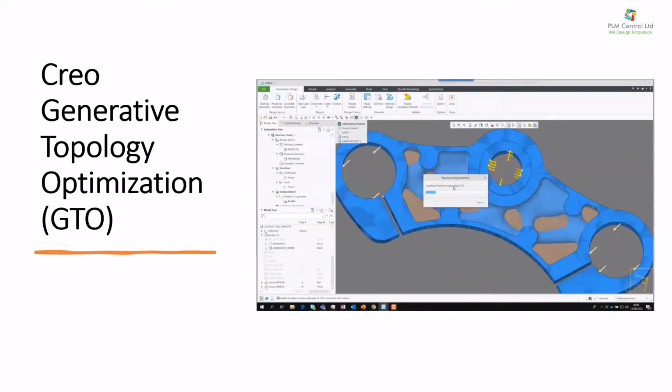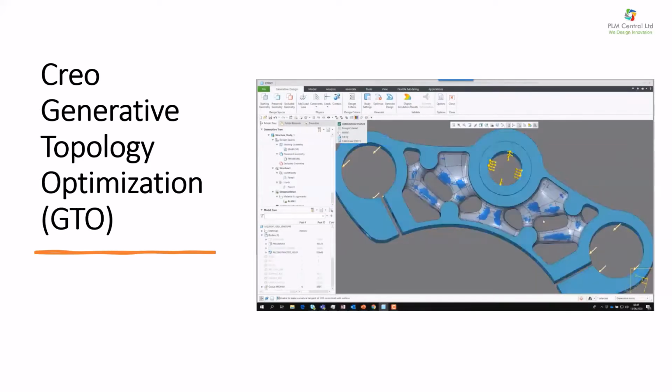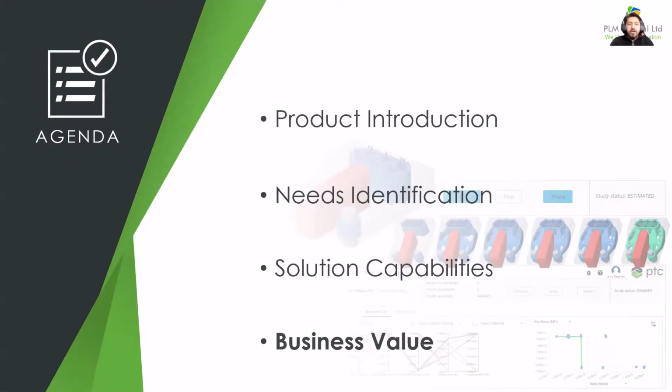You can see it doing that now, and it will start to wrap all of this very complex geometry automatically in these very flexible, curvature continuous, high quality BREP surfaces. Once it's done that, it takes those surfaces, hooks them back up to those intersection curves, and gives us a watertight, solid model, which we can then use in any of our downstream processes, whether that's manufacturing, creating a mold, whatever. Okay, I hope you got to hear that and see that clearly, and it showed generative design in action with a real life model.